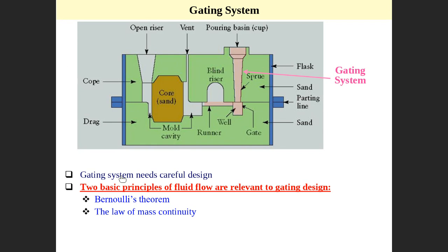There are two basic principles of fluid flow relevant to the design of the gating system, which are the Bernoulli equation and the law of mass continuity. Two equations, two principles, two fundamentals we're going to use to design the gating system: the Bernoulli theorem and the law of mass continuity theorem. Right. So